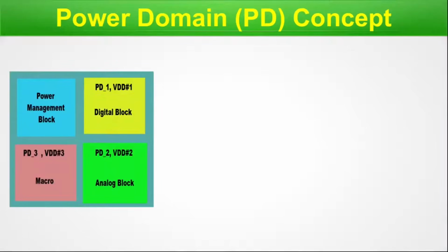Power domain concept. Here, this picture I have shown you in the last episode, but again I am reinstantiating it because there is a necessity. Let me bring my mouse pointer. So if you remember, this is a power management block which controls the entire power distribution of the chip. And here, the different blocks, each with different VDD, are termed as different power domains. Each of these blocks operates its own functionality with the specific VDD they have. So, all internal design elements follow the same VDD as well as the ground of each of these blocks.